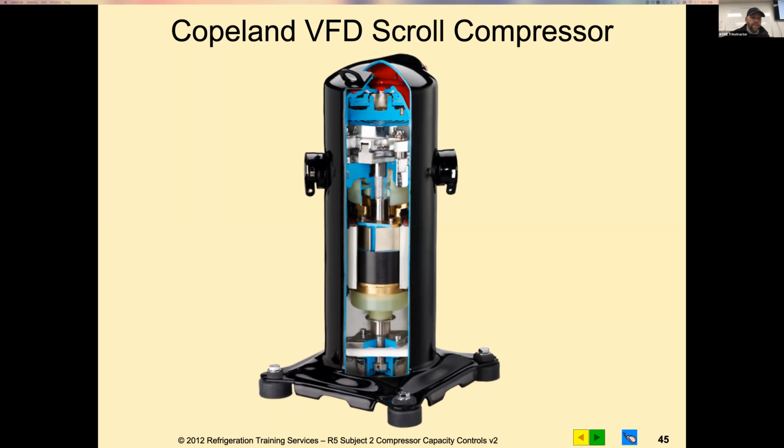These compressors are extremely expensive to replace, and the reason they're set to where they are is because that's where the manufacturer has them spec'd. Do not go outside of those specs to slow it down or ramp it up. If you're still having a capacity issue and you're slowing it way down, then we need to look at other options or other applications.